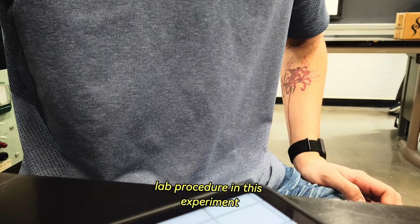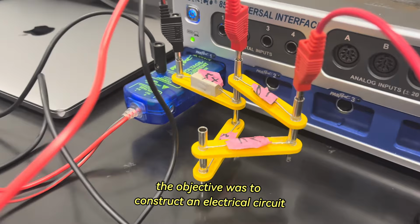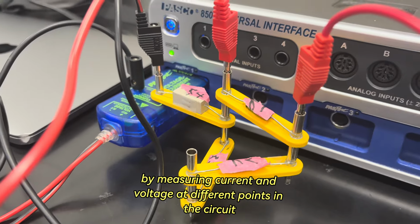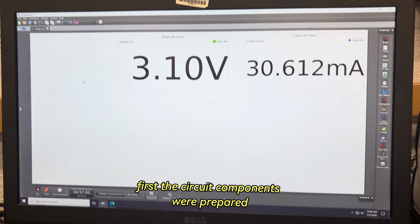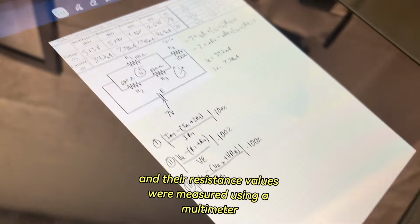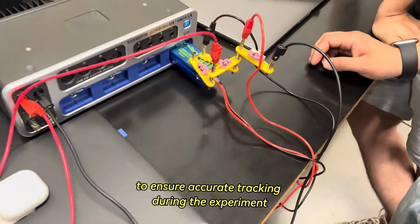Lab procedure. In this experiment, the objective was to construct an electrical circuit and verify Kirchhoff's junction rule and loop rule by measuring current and voltage at different points in the circuit. First, the circuit components were prepared. 4 resistors labeled R1 through R4 were identified and their resistance values were measured using a multimeter. Each resistor was labeled to ensure accurate tracking during the experiment.